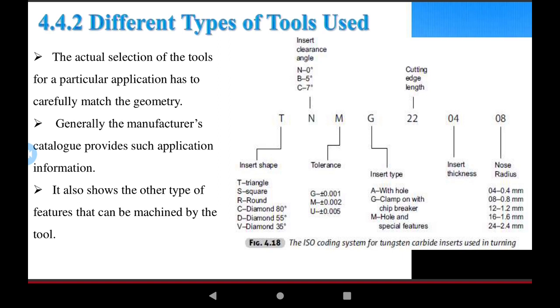Before the manufacturing operation starts and the tools are selected, check and test the materials, the cutting of the materials, the feed rate and diameter of the workpiece, the cut and uncut chip thickness, and other physical parameters used directly on the machine.